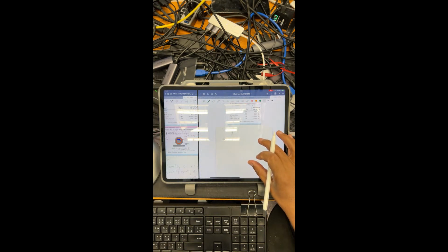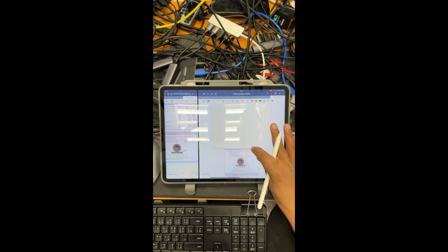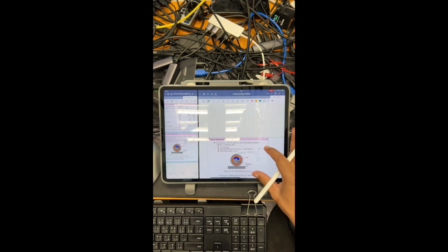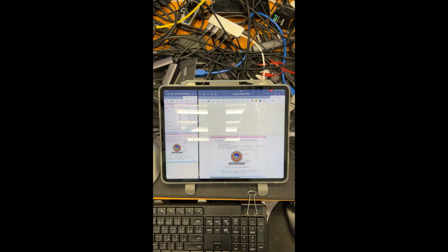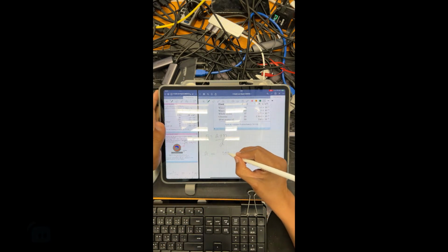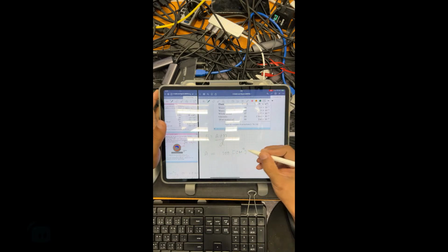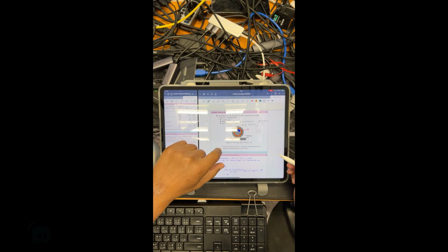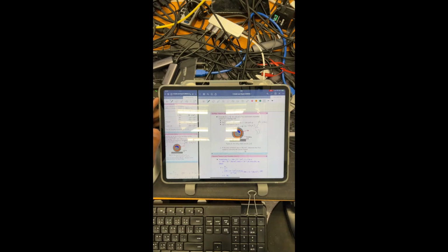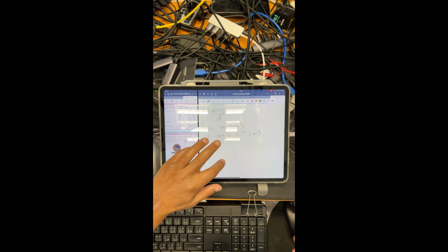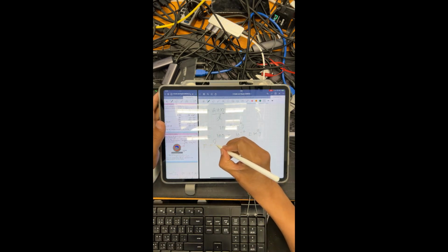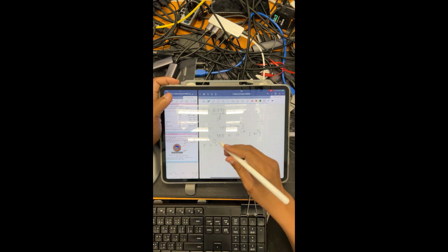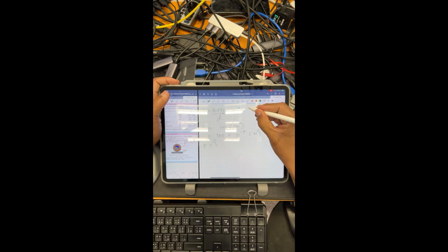A is the area. If the total cylindrical area is 100 square centimeter, so the area is 100 square centimeter, and it's equal to 100 times 10 to the negative 4 square meter, right? And what else? Determine the force needed to overcome the viscous friction. So what is F in this scenario? Anyway, we have to know everything. Velocity is 1 meter per second.